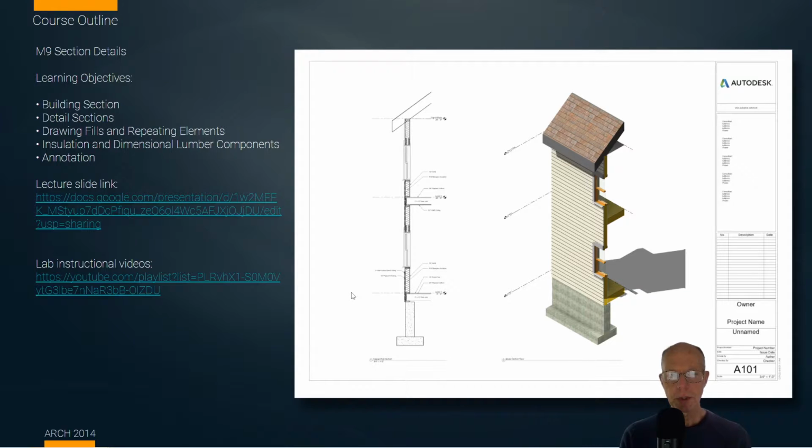In kind of a preparation now for construction tech, this has been in the last few years, we've started to look at helping to prepare students to make the kind of technical drawings that they need to for, well, construction tech and some of the comprehensive studio work. So here we have a really long discussion about what BIM can do and what it can't do. We look at making a 3D model, we place windows in it, and we then see that a lot of components are missing: the headers, the sills and top plates and things like that, the insulation.